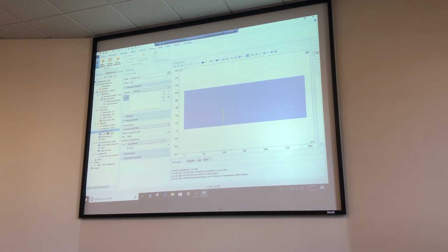Oh yeah, so moving mesh, go to deformation, and then click on 1, and sorry, you wouldn't need that. And then go to moving mesh again, and then right click, and do your fixed boundary. And then click right here, and do Control A to select everything, and then unclick your moving thing. Yeah, exactly. There you go. And then you're done with that. So now we're on laminar flow again. Okay, so I think you're all caught up.